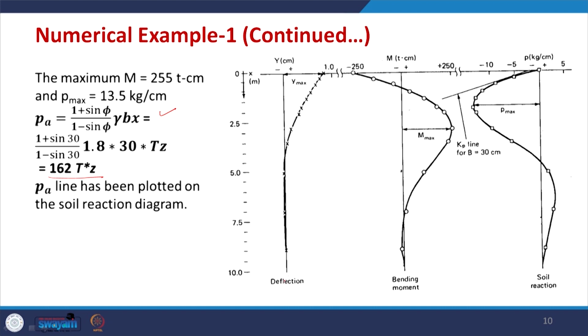negligible at the depth. As for moment, you have one side this side and then the moment starts getting 0, it becomes 0 and then again increases. So, maximum value of moment is at some depth and similarly for soil reaction. But for soil reaction, allowable soil reaction is continuously increased with the depth. So, that means if I continue with this, it will keep increasing while there is this Px keep varying with the depth like shown here.